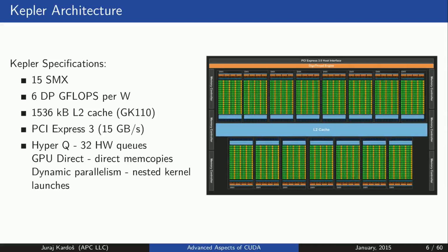Kepler Architecture, produced in 2012, consists of 7 billion transistors distributed within 15 streaming multiprocessors. While the goal of the previous architecture was focused on increasing pure compute performance, the Kepler architecture focuses also on energy efficiency and programmability. Today, the primary constraint on processor performance is the power consumption budget. Having a more efficient process enables us to add more processing cores, thus increasing performance. Kepler achieves 6 double precision gigaflops per watt, while Fermi achieves only 2 in high-end NVIDIA GPUs.